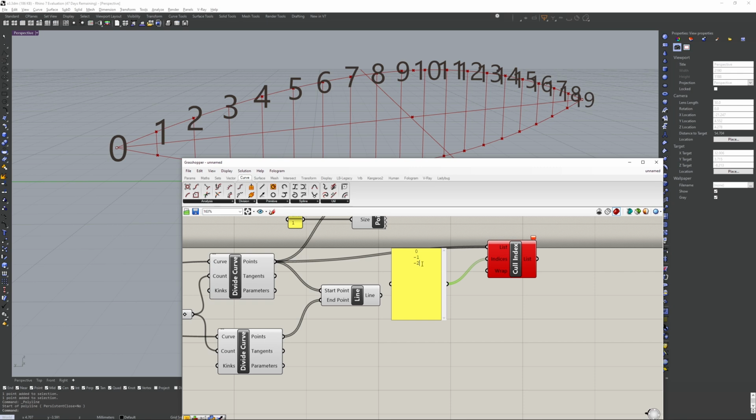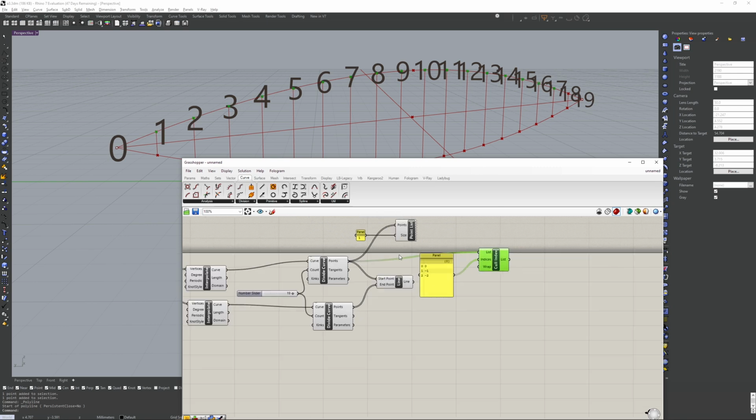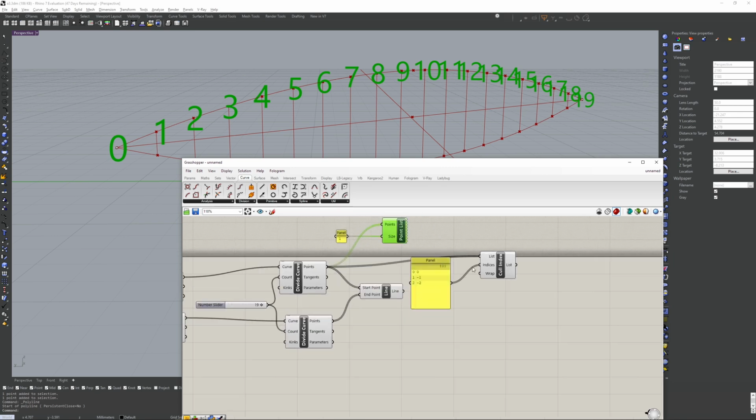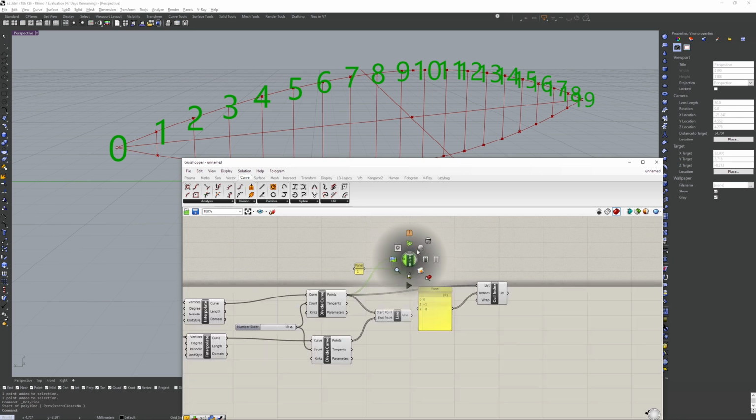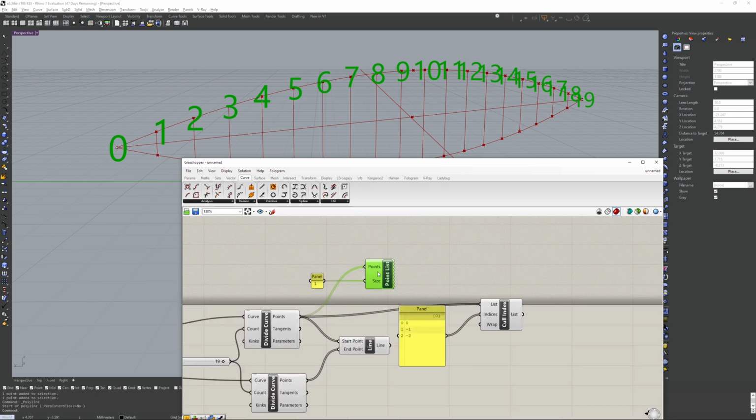You need to make sure there are no empty lines at the end of your list. Okay, I'm going to hide this for now because it's a little distracting. So what I'm doing here is I'm just pressing the middle mouse button, and this will give you a lot of options to disable or enable the block, or I can just simply hide or display it. I'm just going to hide it here.